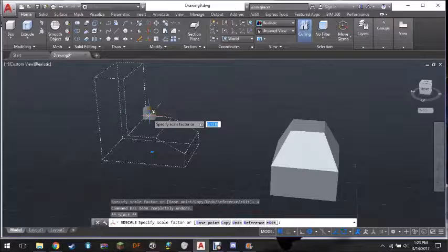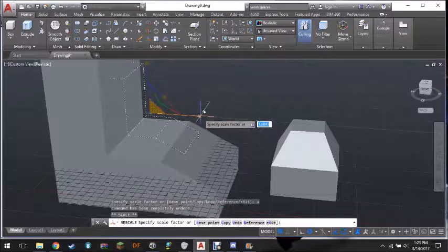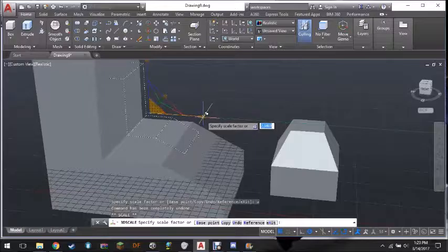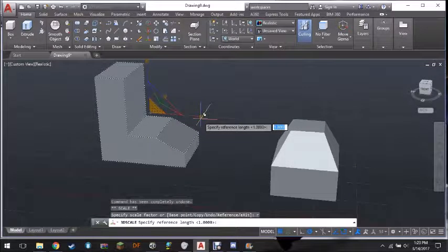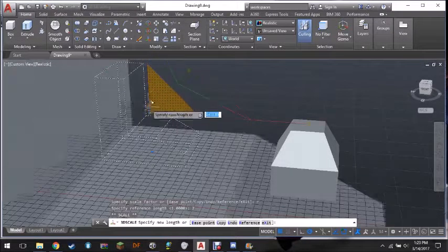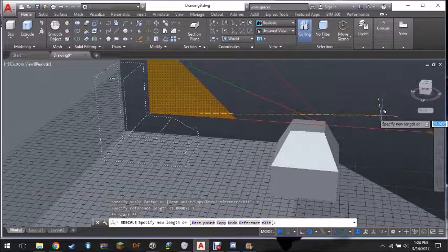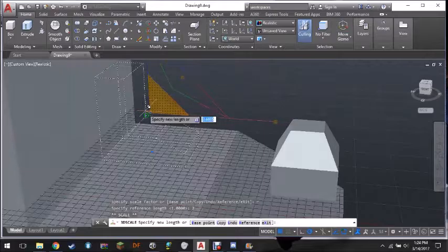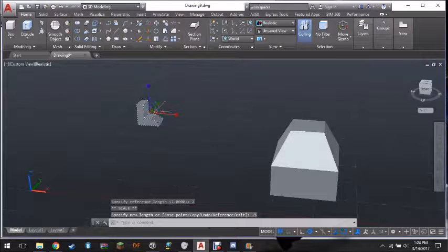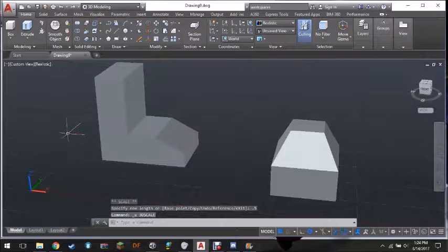Reference means that you can change the reference size of your scale. So if you want the new default to be, say, 2, you can do R2, and then the default size of it is now 2. So scaling it by a lot makes it huge, and scaling it by 0.5 returns it to its original size. And again, exit just takes you out of the command.